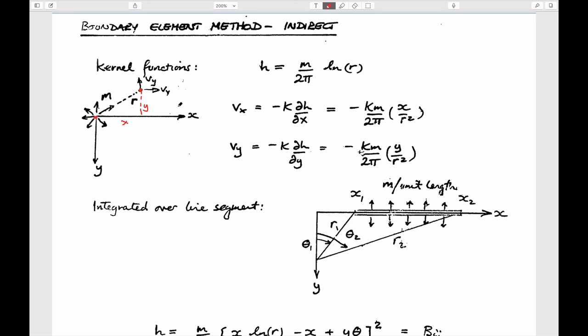We could also calculate, if we know that the velocity in the x direction is just equal to hydraulic conductivity times dH/dx, if we differentiated this, then we could calculate what the velocity was in the x and y direction. And that's all this term is. And you could do that yourself. So coming back to our desire, we want to be able to have some perturbation. And these are called kernel functions, or sometimes called Green's functions.